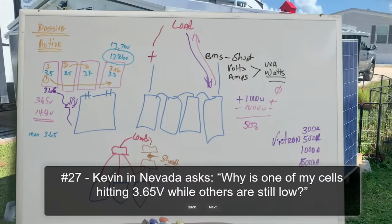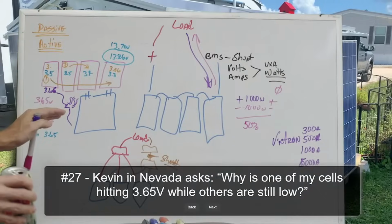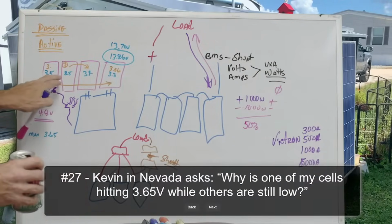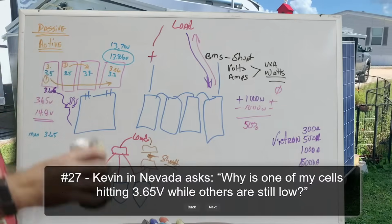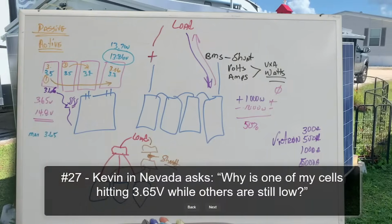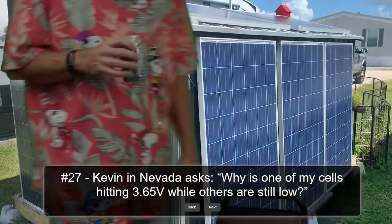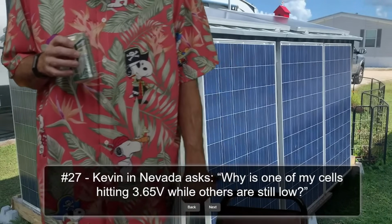That would allow for, because that huge swing in the voltage of the battery is there, then what's going to happen is you're going to shut that off, and it's not going to recover very quickly. And that is why you want to do it that way. Now, the original question was, why is one of my cells hitting 3.65 while the others are still low?